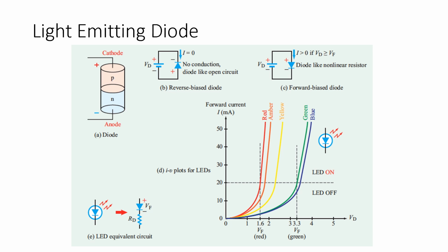The final thing I want you to see about this plot, which I've repeated before but want to emphasize, is that anything over 20 milliamps looks very linear, actually. Anything under 20 milliamps looks very curvilinear, and that doesn't approximate nicely linearly. So this is another reason with these curves why the LEDs don't just immediately turn off if you're slightly underneath the required forward voltage. That's why you get dimming. So that's another interesting part about this too.